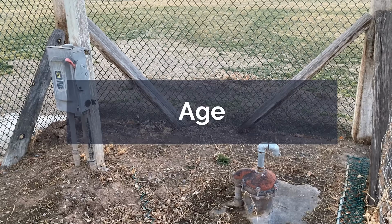And although we're not really going to be talking about this today, keeping track of break data and event data is really, really critical, particularly when it comes to pipe, because the stuff is underground. It's hard to evaluate. It's expensive to evaluate, and knowing how things are breaking and taking pictures of breaks when you've got them uncovered and doing repairs is going to go a long way to help you determine what kind of condition your pipe is in.